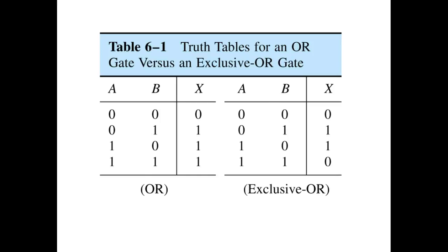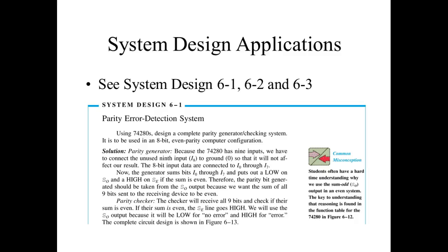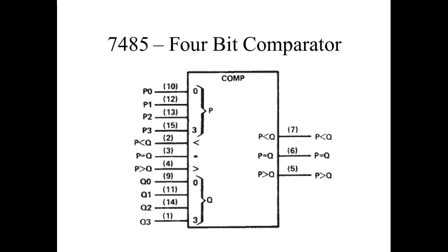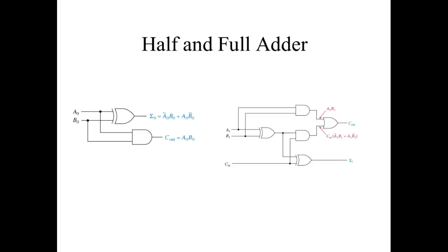And then of course, we have what we call a half adder. That's what they call a half adder. And then they add a little more circuitry to give us what we call a full adder, which would be this right here. So this one picks up the carry from the other module. This would be basically what we use for the least significant bit. And then we take this and feed it into that, then the other two bits, and then we take the carry out and feed it where? To the next one and the next one, and this would do math. So this right here is what we call a full adder, and y'all don't really have to understand how it works.